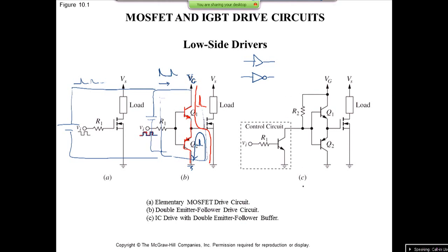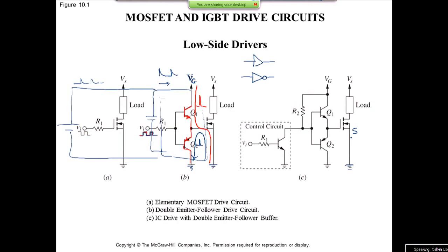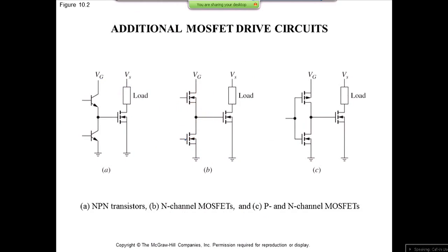So this was all about it, but remember, in all of these examples, you're assuming that your transistor has a source pin that is connected to the ground. All right, and what if that doesn't happen? For instance, okay, here are more examples. Instead of a push-pull with an NPN and a PNP transistor, you can use two NPN transistors like over here, or these transistors do not necessarily have to be BJTs. They could be FETs as well, like the examples that we have here and here, and also here, but it's basically the same thing.